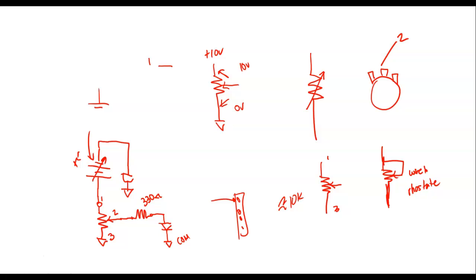Now we can set it to anything up to 5 volts, though we'll never get it all the way to 5 volts. First, you're going to measure across your diode. We can set it at 0.5 volts, or 550 millivolts, and we measure across this right here.